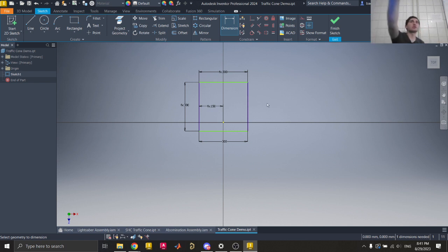So, question? How are you changing one side's dimension without? So that's with referencing it in other dimensions. If I type in a thing here, I can either type in the name of the dimension that I want right here, or I can also just, in the little text box, click the other dimension I want to reference, and it'll just auto-populate that number in. So then I'll just hit the checkbox, and then, yeah. So, yes?